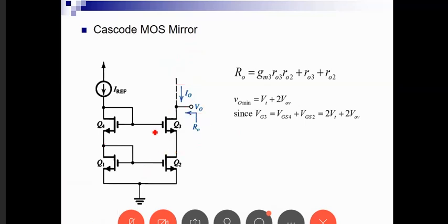now the shared voltage, what it is. So if we look at VG3, if this is gate 3, we know that gate 3 is equal to this voltage from here to here, and then from here to here. So VG3 is really VGS4 plus VGS1, okay? So if VG3 equals VGS4 plus VGS1, which is VGS2 basically,